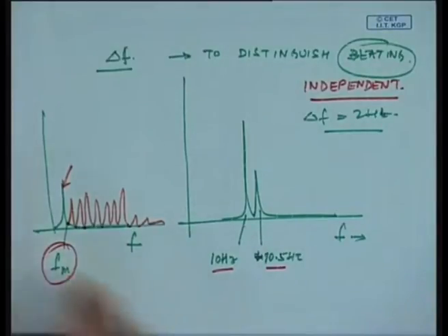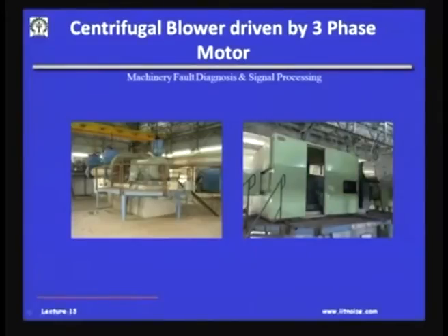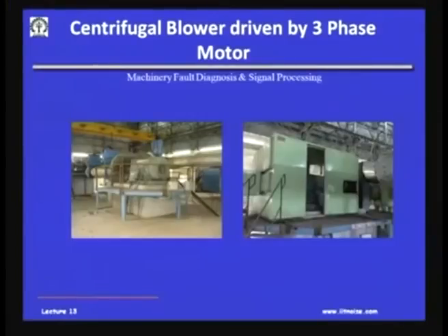Okay. Now, in a plant like this, I should just mention to you that in fact, we at IIT Kharagpur had designed this enclosure for them just to kill this noise which was generated because of the beating. Because again, if I have one machine generating 100 decibel of noise, another machine of course another 100 decibel of noise, the sum effect will be 106 decibels, but because of beating at some frequencies there will be a large amplitude and that amplitude will be very loud. So, to reduce that we can put an enclosure wherein you can put in a lot of lining material.